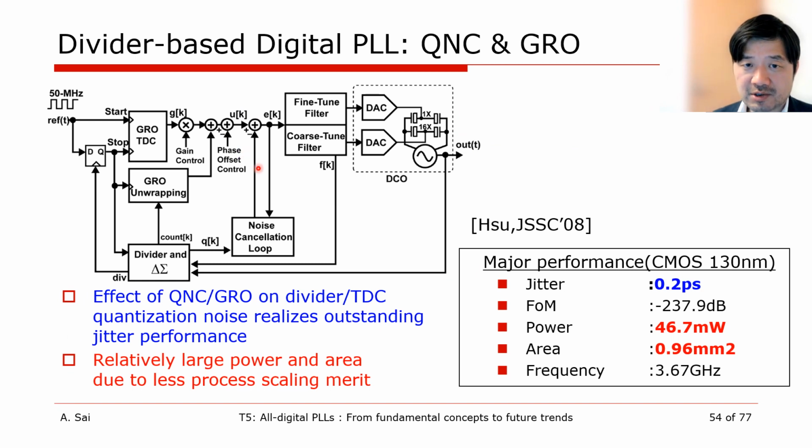This slide shows the divider-based digital PLL with gated ring oscillator noise shaping TDC and quantization noise cancellation circuit. High resolution digital phase detection is performed with noise shaped GRO TDC.